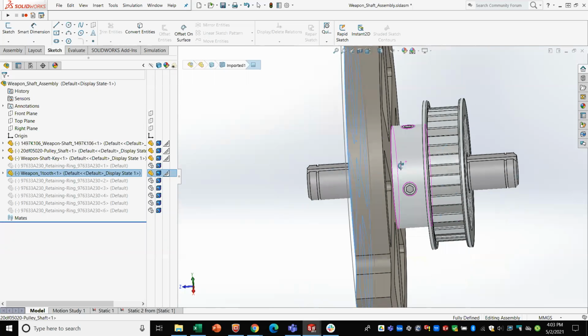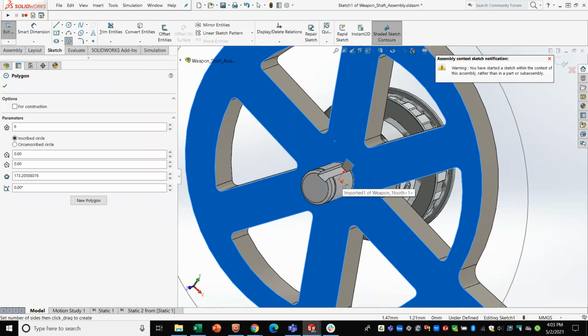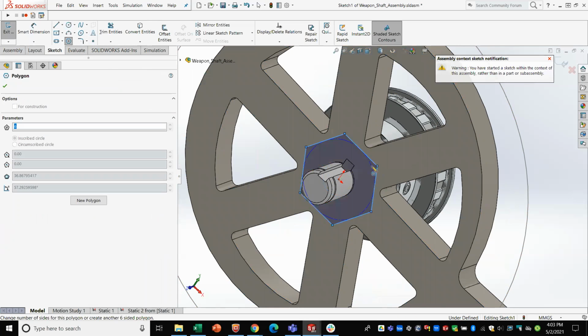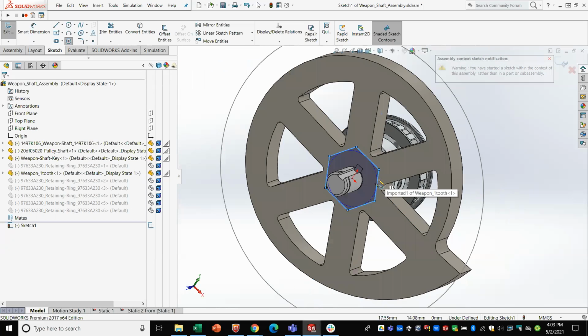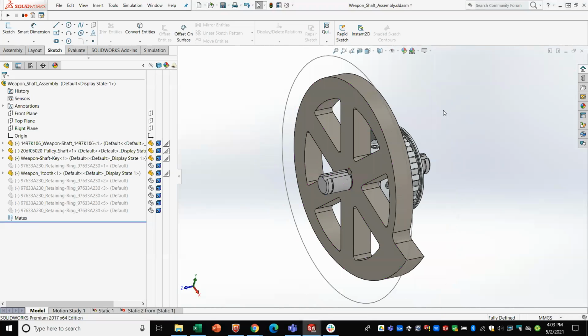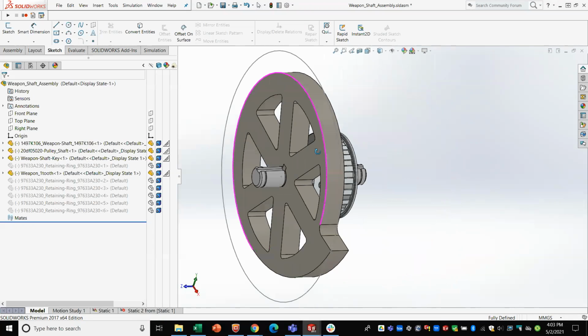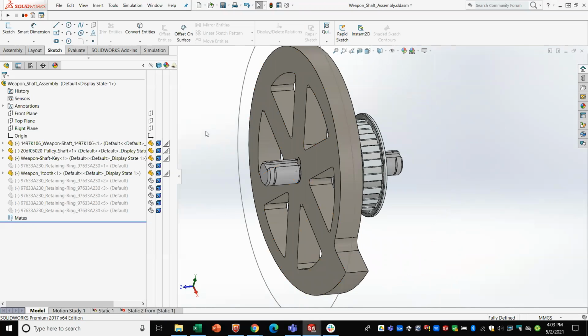And then I bolted the hub to the weapon disc. Yeah, that's using screws just sideways. That's pretty similar to how our other 15-pound robot is designed. It's a vertical spinner though. In my experience, this hasn't been the place that has failed, so I figured it's worth trying different things.